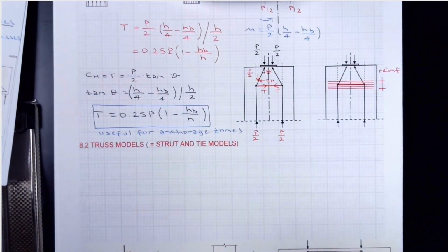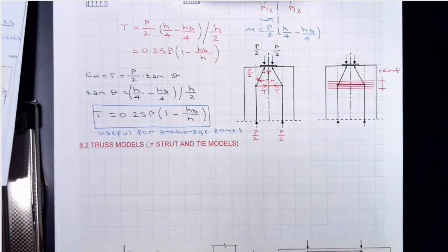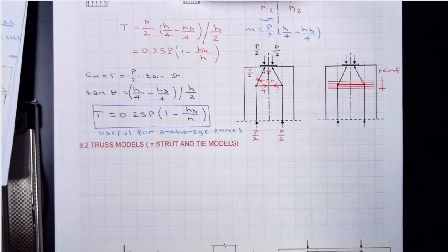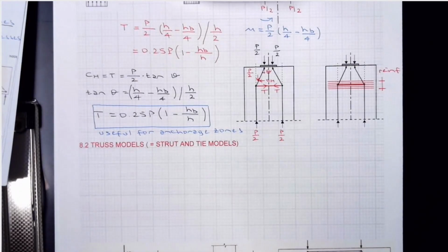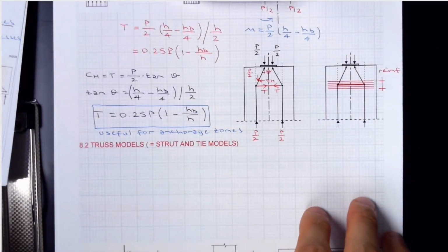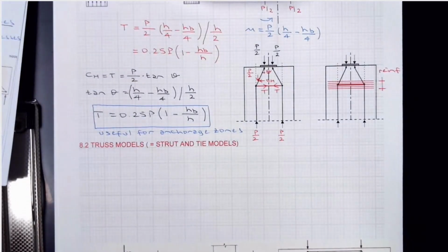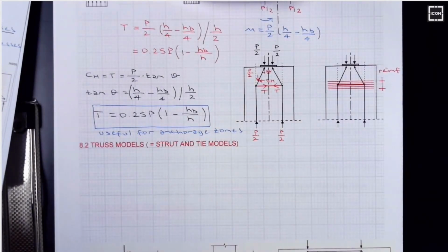I'll come to that. So that is my example. I created that example for you because I was expecting that would be interesting to you. So actually there's going to be two sets of reinforcement needed, right? There's going to be spalling reinforcement needed close to the face, which I think is what you are referring to in this region, which is pretty close to the base plate.